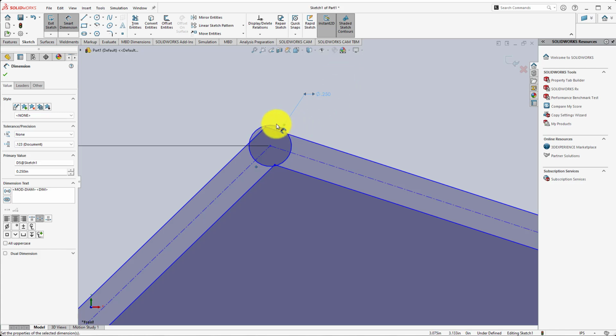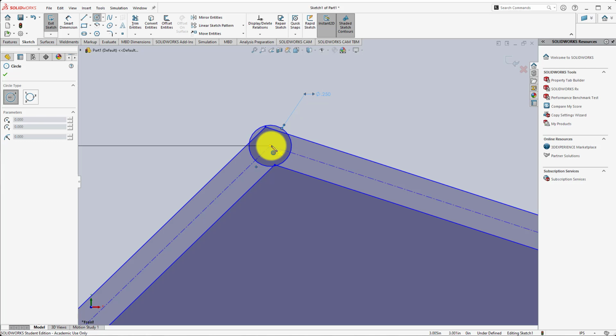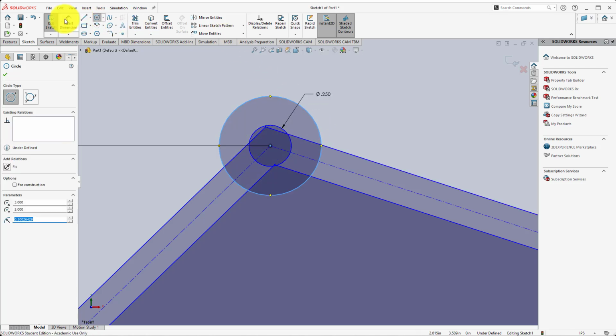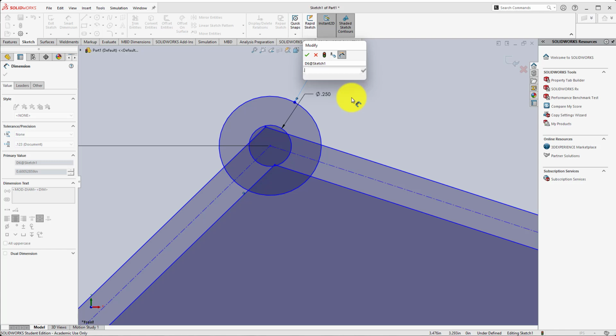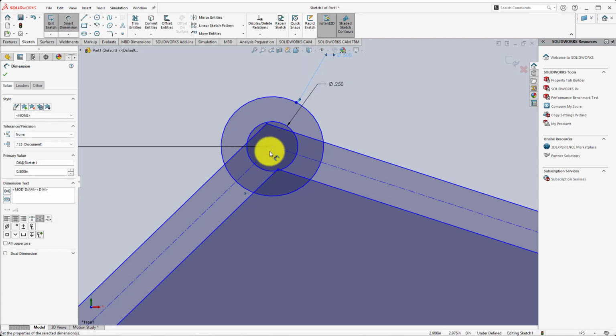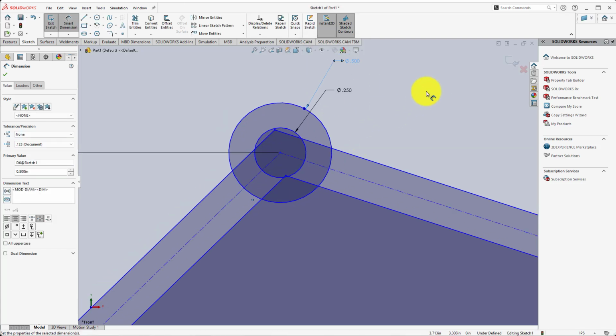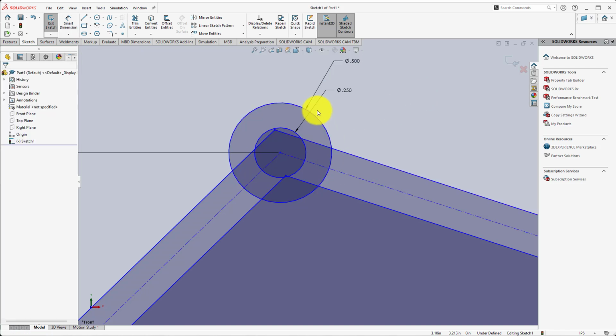That's going to be the hole that the laser is going to cut for this. So we need another hole. And if you notice, I hover over that, that's concentric about that circle. I'm going to make this one half an inch in diameter here. There we go. So 0.5. Now then, I have both of my circles drawn.